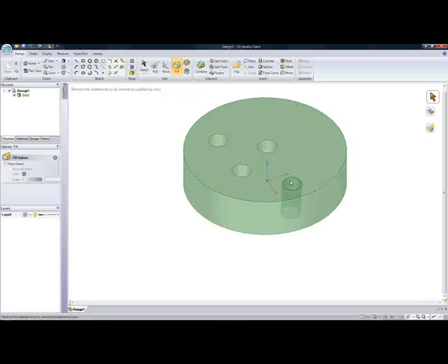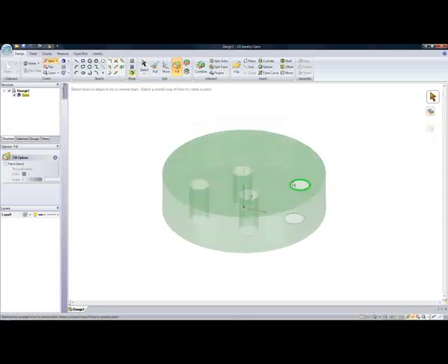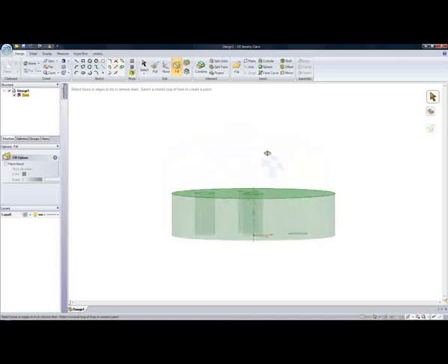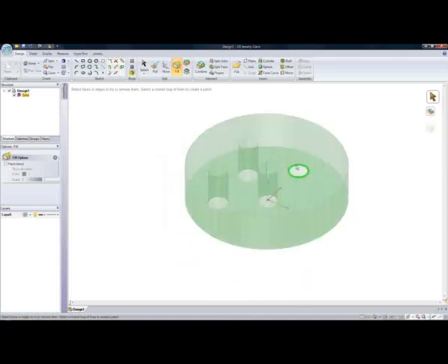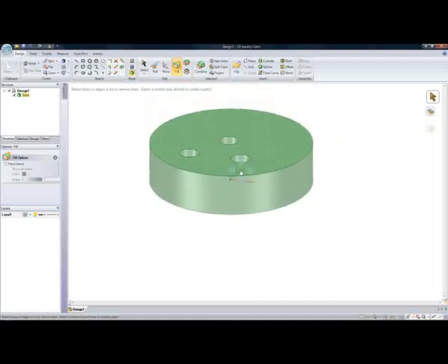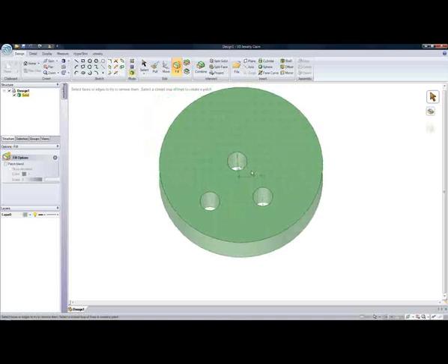I'm going to take this hole again and I'm going to delete the inside surface. By doing that, it's a ghost again. However, this time I'm going to fill it individually. So I'm going to select that one, and I can select Fill, and it remains a ghost until I close all the naked edges. If I select that now, I can press Fill, and it's now closed. I'm going to select this inner surface, just click Fill, and close it.